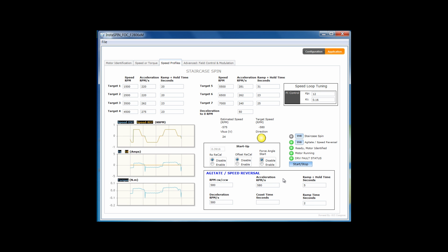And this shows very nice capabilities of the sensorless algorithm moving through zero. And you'll notice we pause slightly at zero speed before we take off. And FAST is tracking in this location and can provide the needed torque. If you pause longer at zero speed, you may get into a situation where FAST has slightly lost the angle.